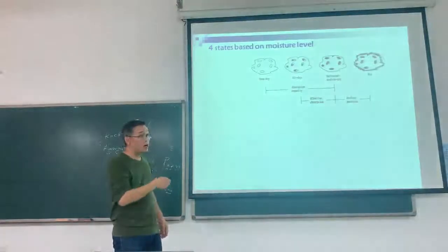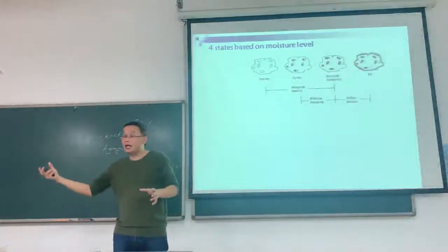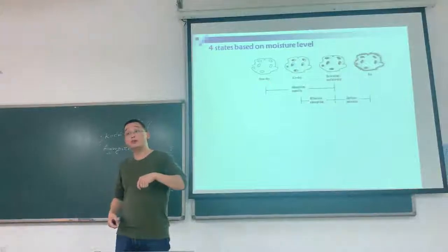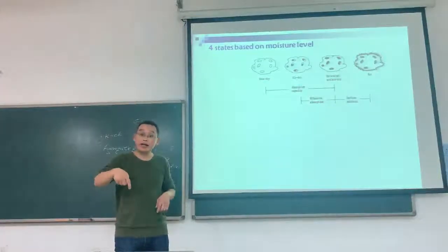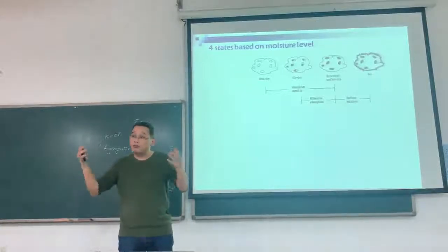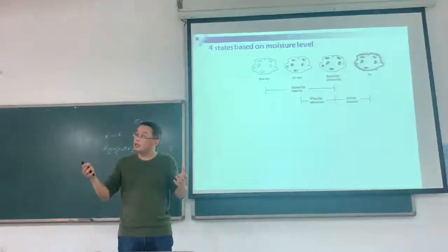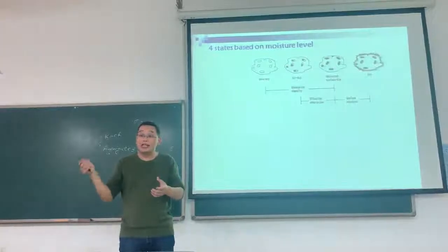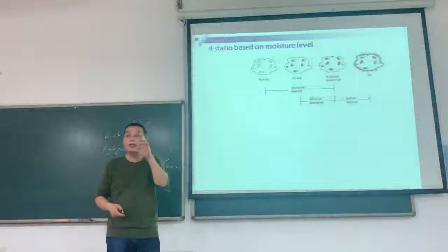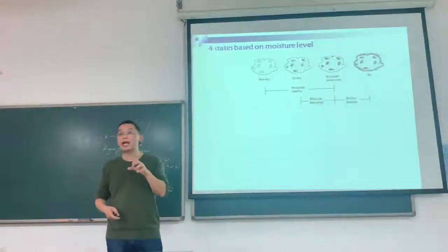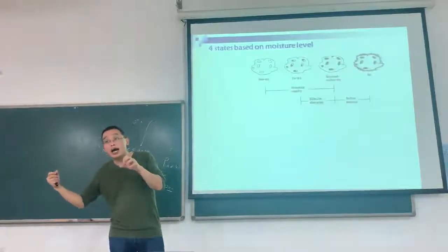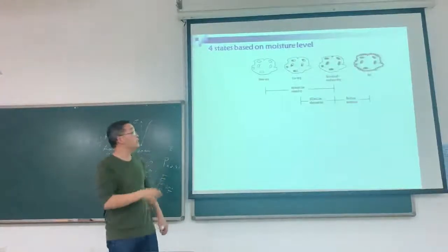So we can get that. If we put the aggregates inside, just like in the classroom, and the weather is not changing, but maybe it is sunny for a week, and then the aggregate gets dry because the moisture in the aggregate is equivalent to the air outside. So this is the air dry.